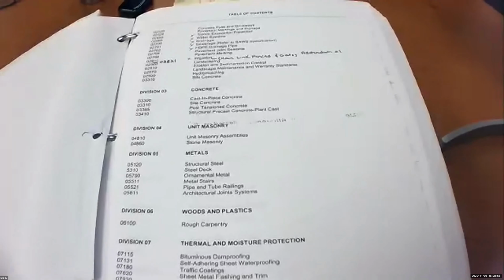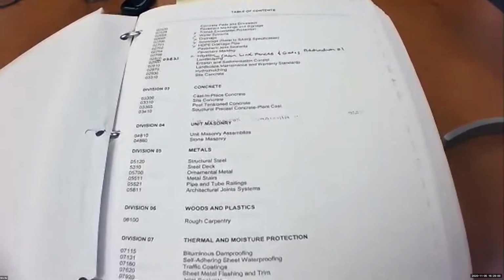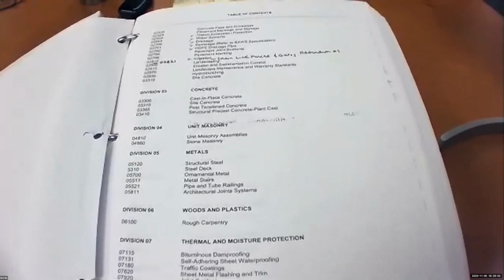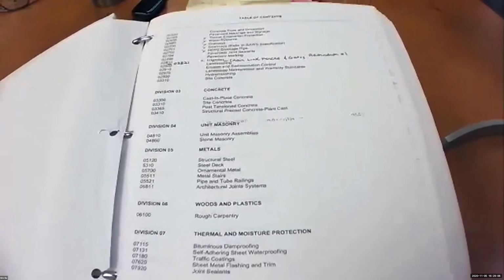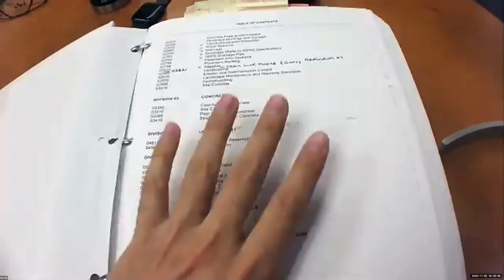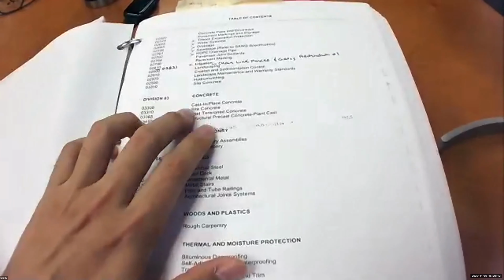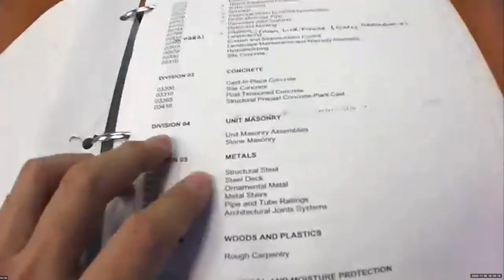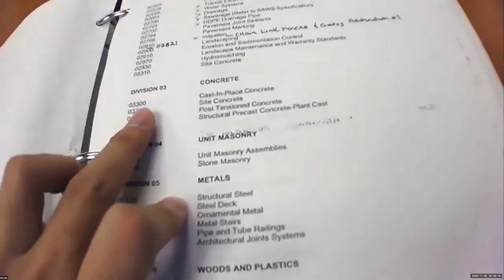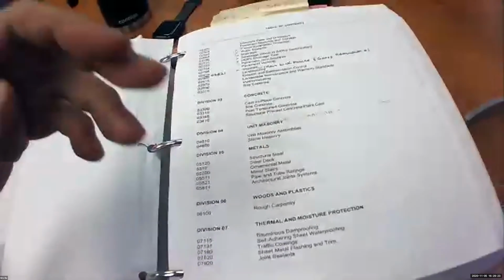What's the CSI? Construction Specifications Institute. They publish something called MasterFormat. The majority of construction companies, I think about 60%, are using this one to organize their estimates and their costs. So let's say I'm working for construction company ABC and you are working for a different construction company, but if I say I'm talking about 03300, you know that's about cast-in-place concrete because we are using the same coding system.